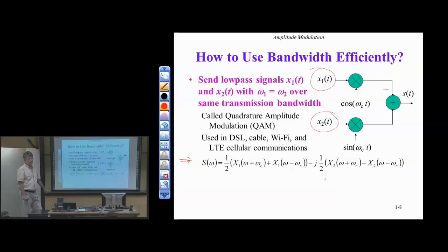Doesn't it know it already? It knows what it is approximately, but there's always some error. The clock at the transmitter is different from the clock at the receiver, and then the transmission medium can wiggle that around a little bit. There's some distortion of that as the waveform propagates through the channel. So we know it to a certain amount of accuracy. We just have to then lock onto it and find it. The good news is there isn't a huge window to look over. Maybe there's 1 or 2% error, 3% error. It's a very small amount of error. So that's good. It means we have a very small window to look over.